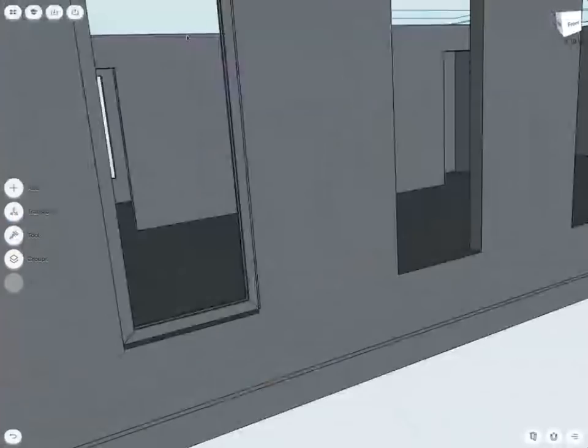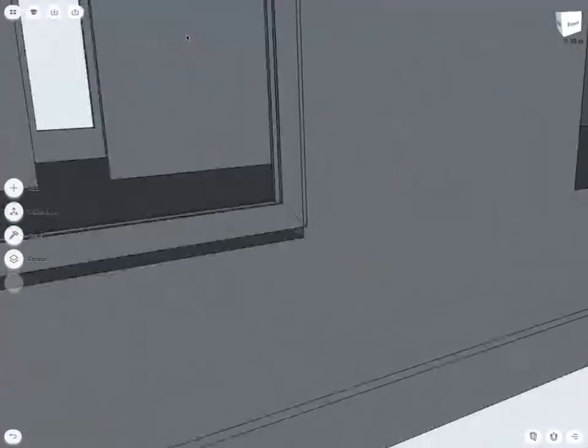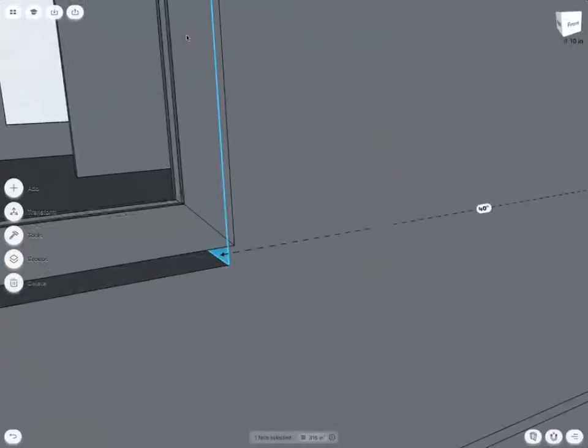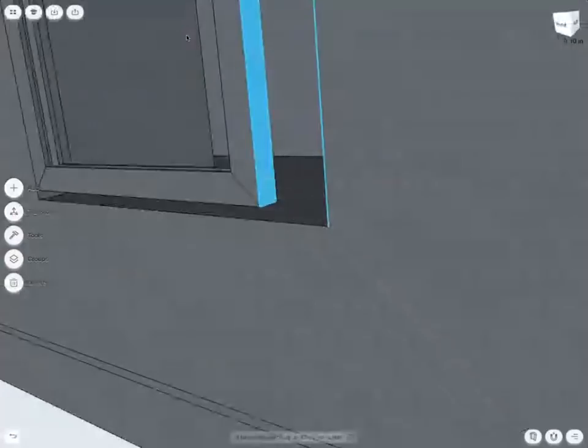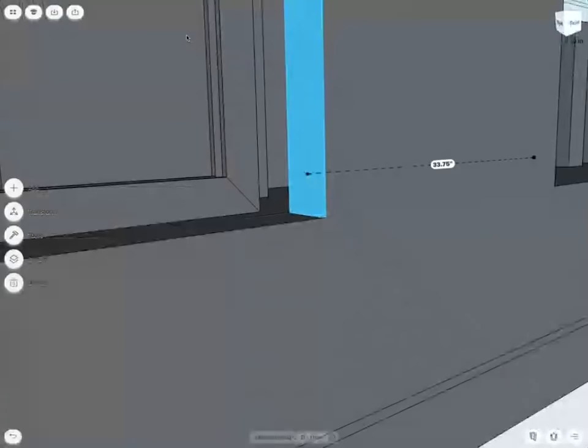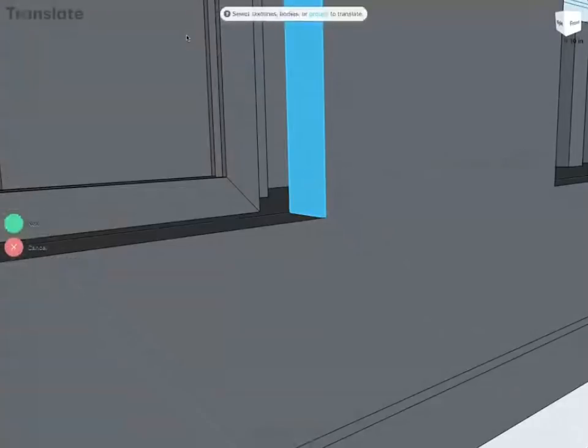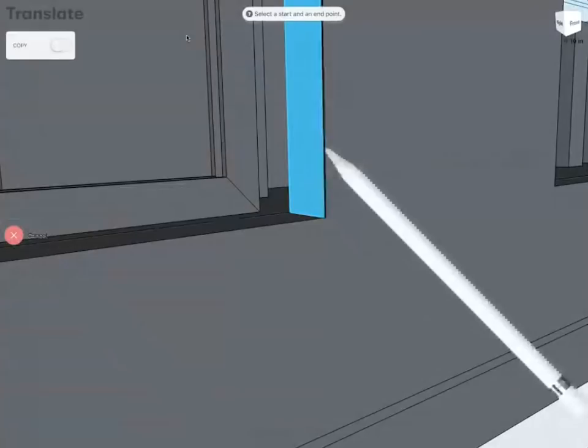And how do we now fix this problem? Also here, this is a nice case to show you the power of the direct modeling. Our window opening is a little bit bad. So let's say this is part of the initial dirty modeling. Not everything is perfected yet. And now in the CAD model, we make everything tidy. This edge, this face I will select with the pencil and then drag to the right side. And I could select this face and select this face, and it tells me exactly the distance, lower mid part. And that is the amount, so 5.869 inches. I have to move this face to the left, but I'd rather let Shaper do the work for me. So I go, face selected, translate, go next, and then say U to U and done.